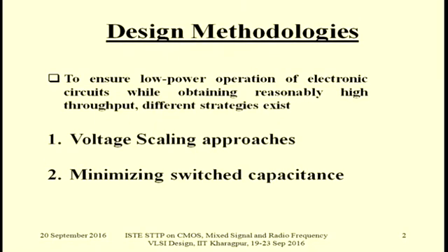And secondly, although it accompanies the first one, if you recall the expression of power, it equals the product of the switched capacitance, the square of the power supply, and the frequency of operation. So both capacitance as well as power supply are closely involved in the expression of power.